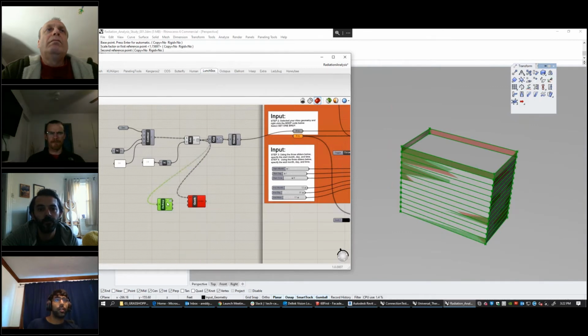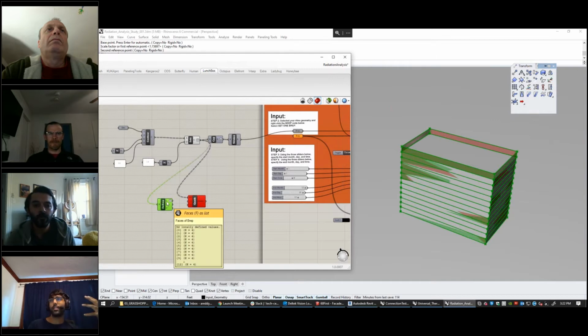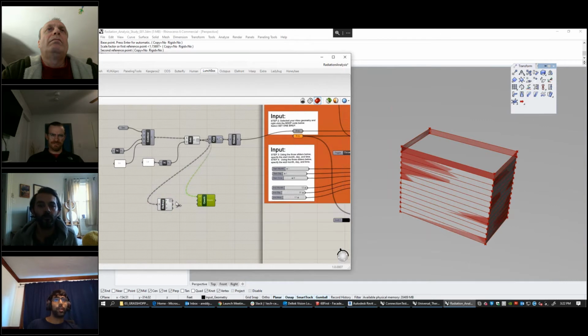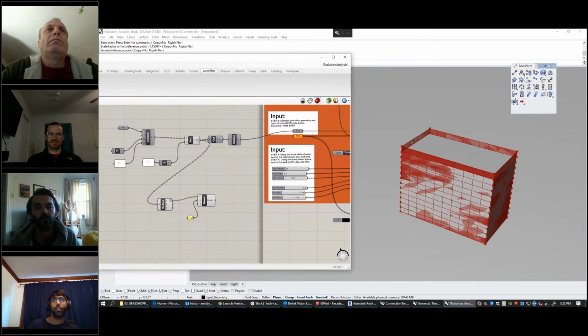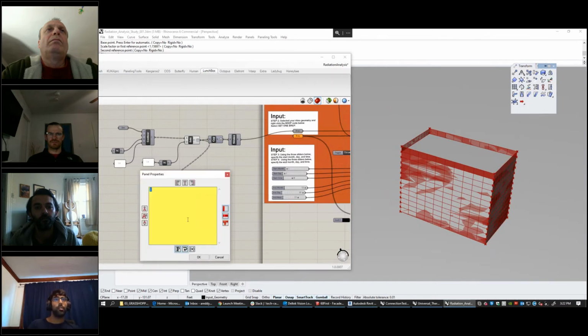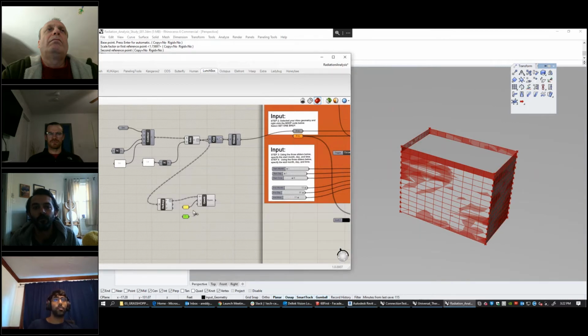We simplify 1 through 12 layers. That's 1 for each floor because we did our contours up like that, and then 4 faces for each one of those levels. I'm just going to do it quickly with the UV, because you could really specify based on the length, the V division, and all that. Just to get through this quickly, vertically we're going to have one panel per floor, but going across, let's say you've got 10 divisions.